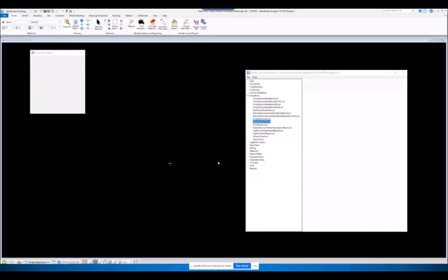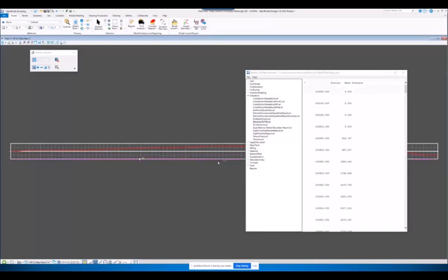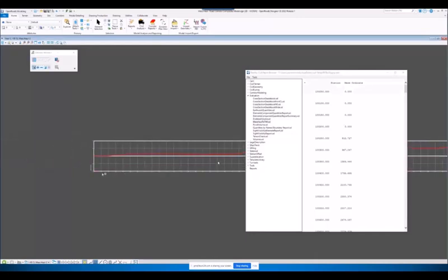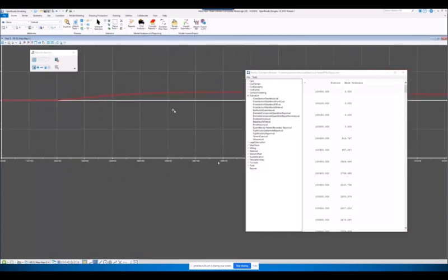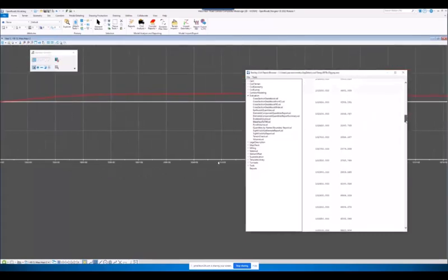So it's going to plot that in the XML report for the mass haul. You can see the mass ordinate being placed there, and you can see the mass ordinate being plotted on that more or less profile space, showing you the balance points and which way you should move dirt. Obviously, this is mostly cut here because we're mostly moving pavement out. It's not like we're adding additional lanes in this region, but still, it gives you an idea which way the dirt has to move. And as the construction sequence continues, I could look at the southbound the same way I just did it in the northbound situation.